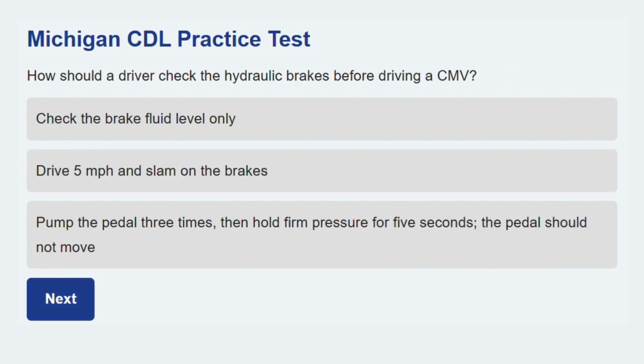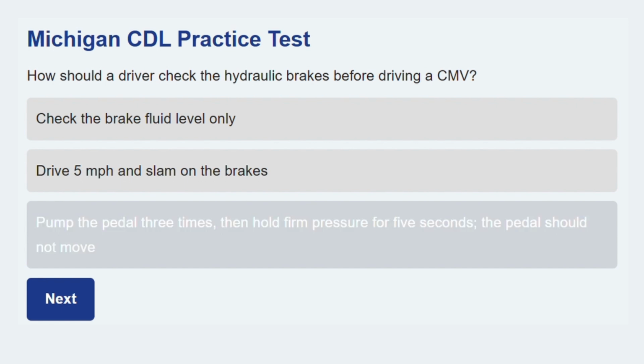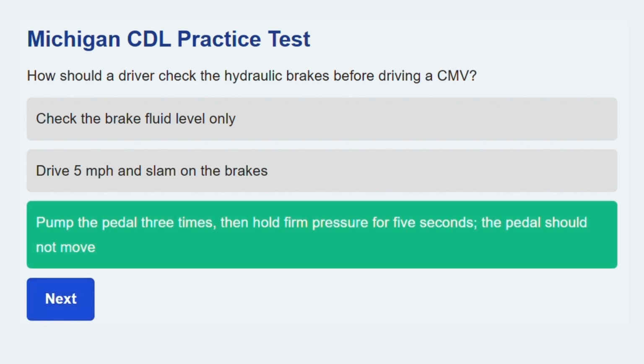Let's continue. How should a driver check the hydraulic brakes before driving a CMV? Pump the pedal 3 times, then hold firm pressure for 5 seconds. The pedal should not move. If the pedal moves or feels spongy, there is a leak or defect.